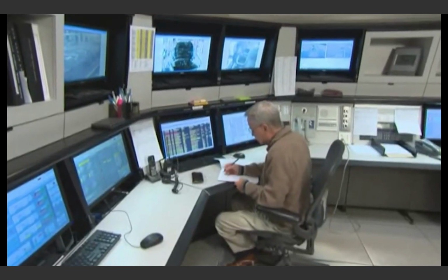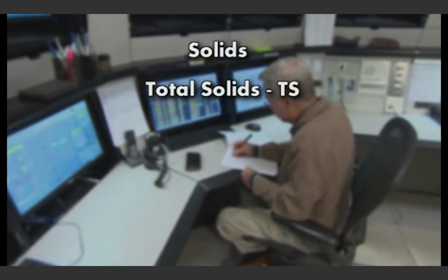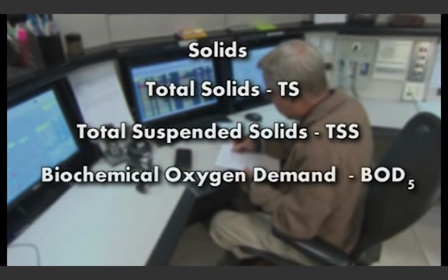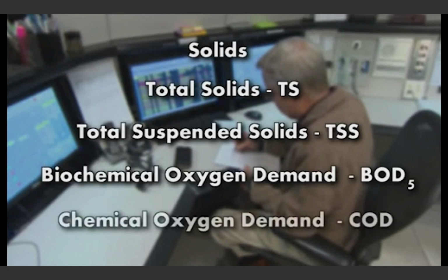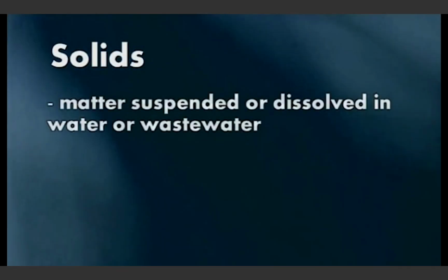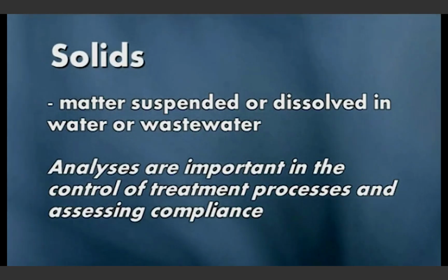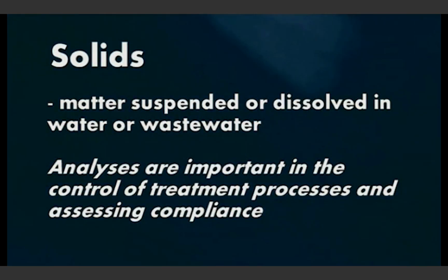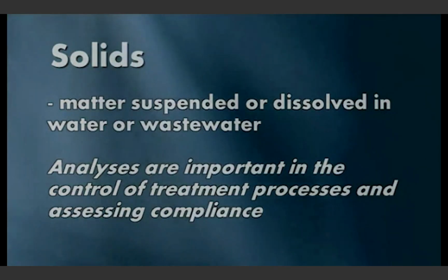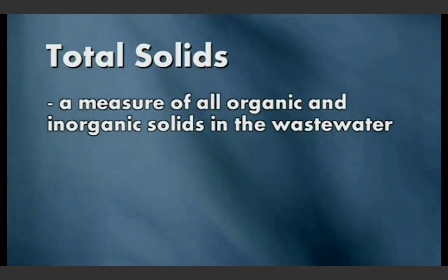Here are some essential terms and abbreviations operators should know: solids, total solids abbreviated as TS, total suspended solids or TSS, biochemical oxygen demand or BOD5, and chemical oxygen demand or COD. Solids refer to matter suspended or dissolved in water or wastewater. Solids analyses are important in the control of biological and physical treatment processes and for assessing compliance with regulatory agency wastewater effluent limitations. Total solids are a measure of all organic and inorganic solids in the wastewater.